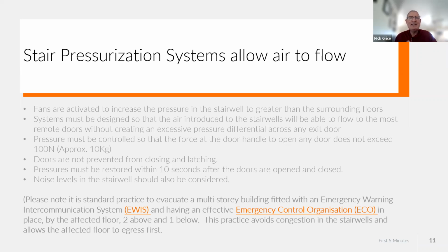So the force of a handle shouldn't exceed 100 newtons, which is about 10 kilograms. For doors as well, once they're open and people have gone through it, they should be able to be pushed and latched shut by the airflow, and pressure should be restored within 10 seconds.